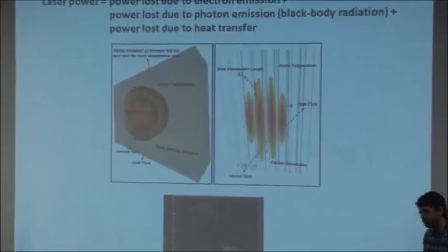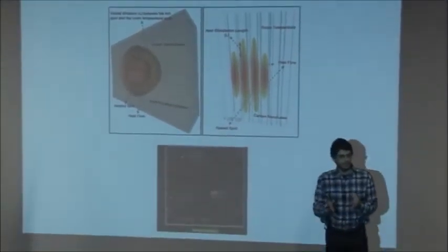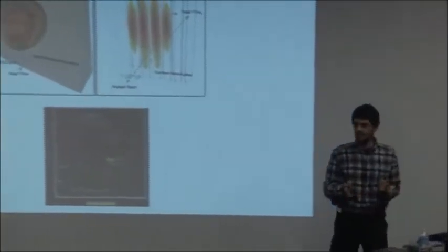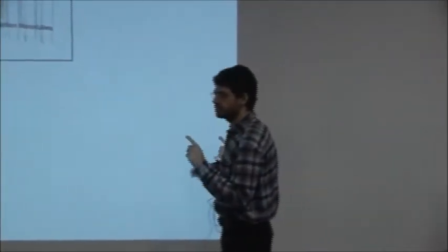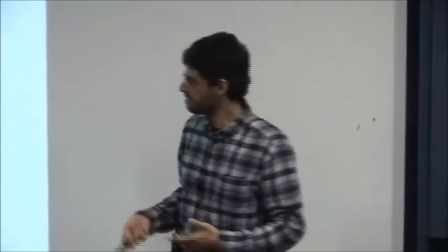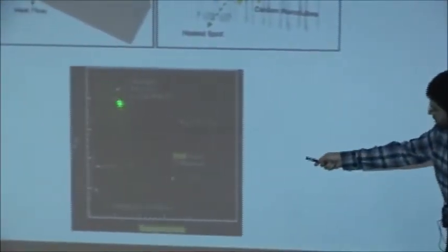There's also something else that one has to realize. I said thermal conductivity of nanotubes is high, but thermal conductivity at what temperature? Because thermal conductivity, like any other material property, could be a function of temperature. In fact, for any material, this curve is thermal conductivity as a function of temperature. If you go to really high temperatures, the thermal conductivity drops, typically as 1 over temperature. And this is basically due to Umklapp type scattering.